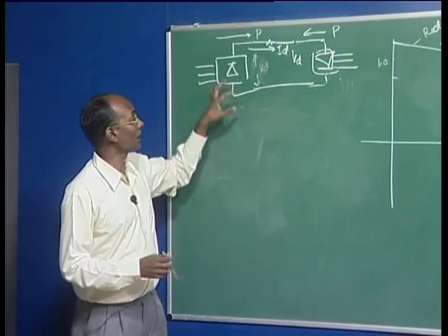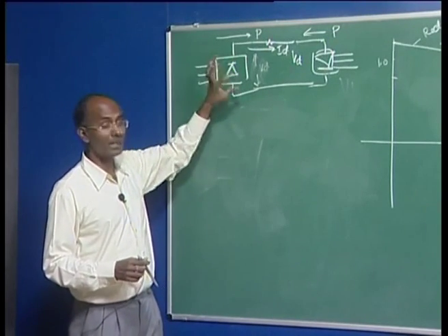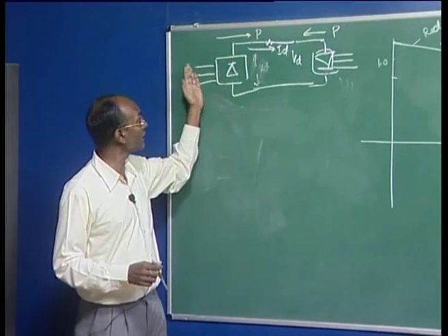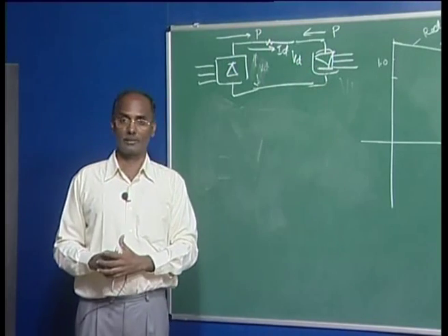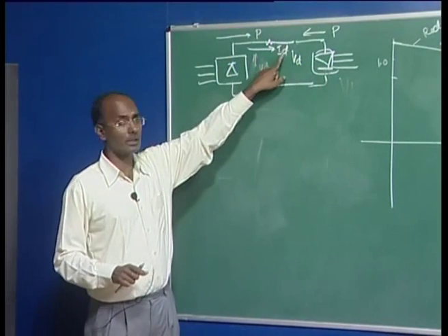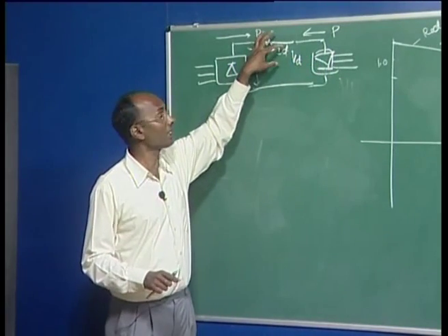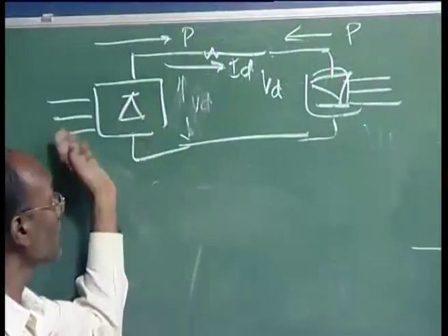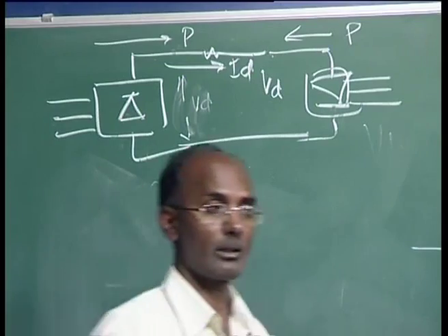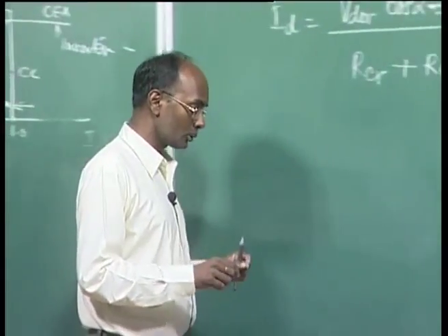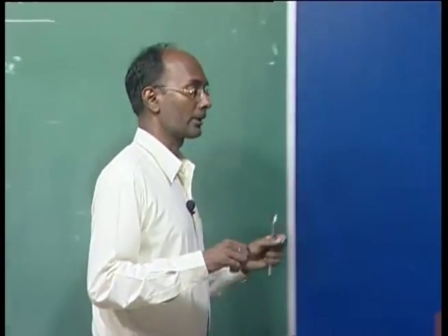And at the same time, you are firing in such a way that the reactive power requirement will also be excessively high. The higher current may damage your converter stations and can also damage your line, and a huge reactive power requirement will be there. Therefore it is better to use voltage and current controllers rather than power controllers at either end.